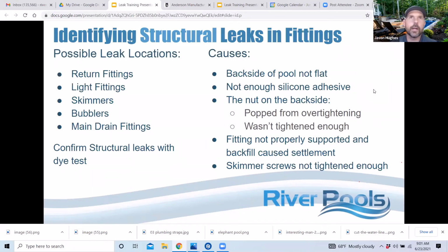And by the way, our regular light fittings, when we put the lights in with the micro bright lights, we pull the cable through, we lock the light in. That does not seal that. That's why the conduit floods. And they are Pentair, there is a way that there's an O-ring and some lubricant, and there probably is a way to seal that, but we've been able to mostly seal it, but we don't ever count on that being sealed 100%. We always count on the fact that light fitting is going to leak some.